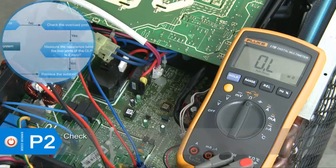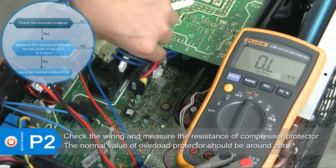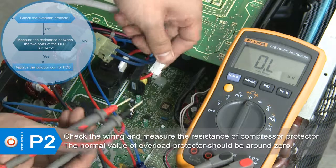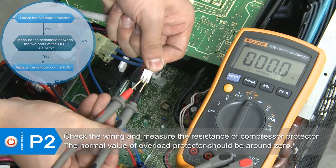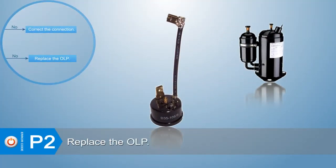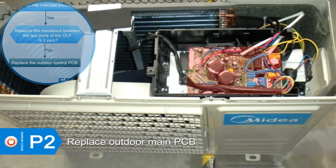If the temperature of the compressor's top is lower than 100 degrees Celsius, check if the wiring of the overload protector is well connected. If the wiring of the overload protector is good, check the resistance value of the 2 ports of the overload protector. The normal value should be around 0. Otherwise, replace the overload protector. If the error still exists, replace the outdoor main PCB.